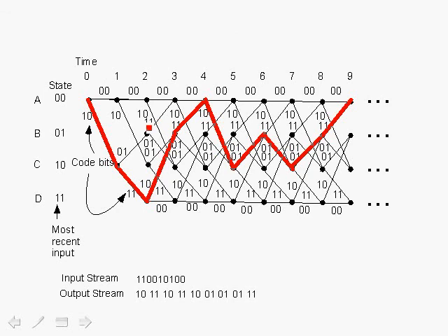And what happens with the convolutional encoder is that the coded bits depend on the previous bits, in a particular way that the convolutional encoder works, that is, it depends on memory and all the previous bits. And given the trellis diagram that you see over here, convolutional encoders can, by increasing the constraint length, and that is the dependency of the existing bits on previous bits, achieve a larger and larger minimum distance. And of course, the power of the error correction capability of a particular error correction code depends on the dmin.